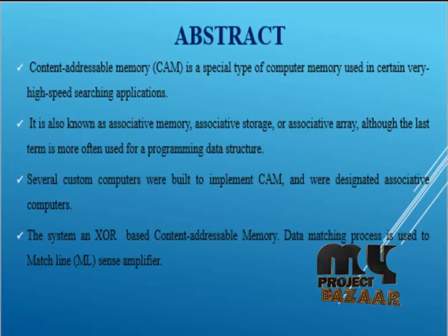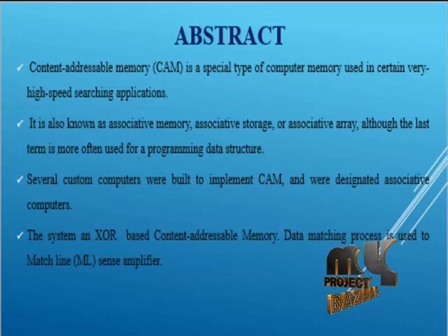Now we are going to discuss our product abstract. A content-addressable memory can comprise memory elements usually built with the 6T SRAM cell and circuit to compare the search bit against the stored bit. We implement the NOR and NAND type of MLs and the two basic processes of our product.